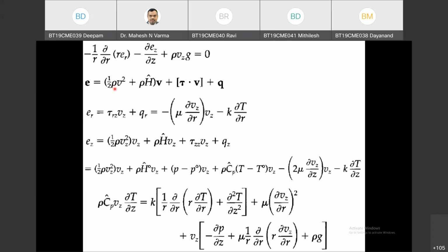Yeah. So this is what I was telling actually. This will have three components. This is not purely convective. So enthalpy you write in terms of internal energy, and this pressure will go here actually. That will be molecular flux because of pressure fluxes. That is added here. So this you can take as the convective flux. This is the work associated with the molecular transport, and this is the conductive flux. Okay, hence ER.